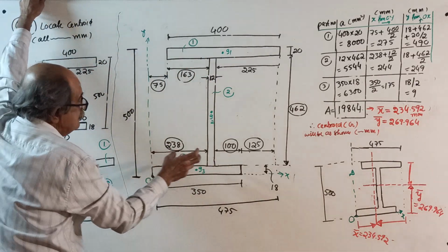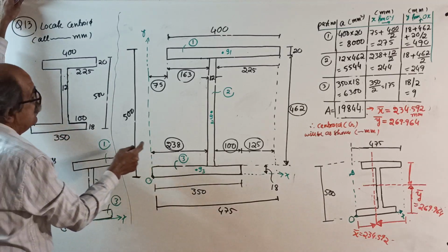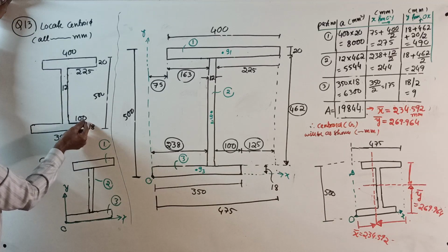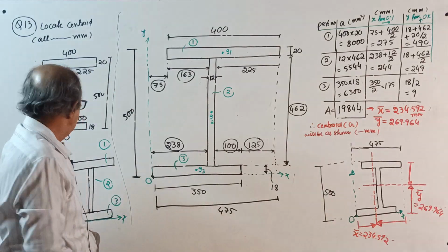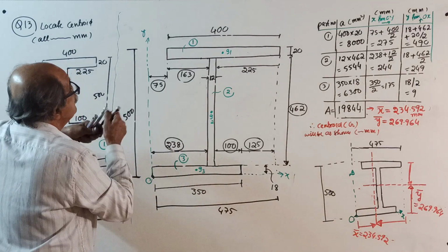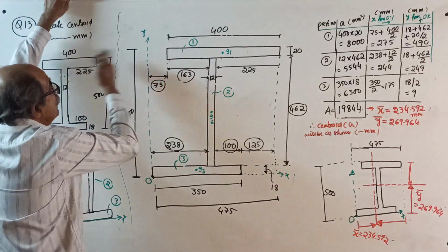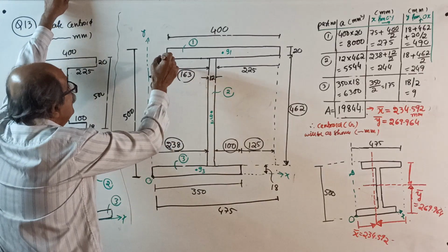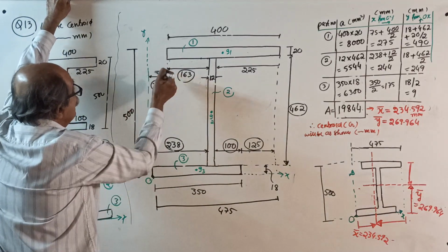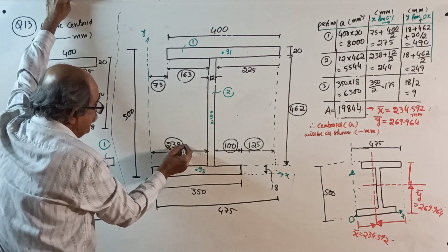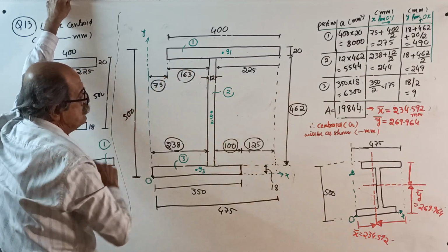Okay, then this offset you require. How? See, total is 350. From 350, subtract 100 and also subtract 12. So, from 350, subtract 112. You will get this offset 238. This offset is 163. This is 238. So, this point will come much further left side. See here, from here, this is the edge. See, your YY is at the edge here. But there's a gap here. I want that gap. So, once you get 238 here and 163 here, from 238, subtract 163, get 75.